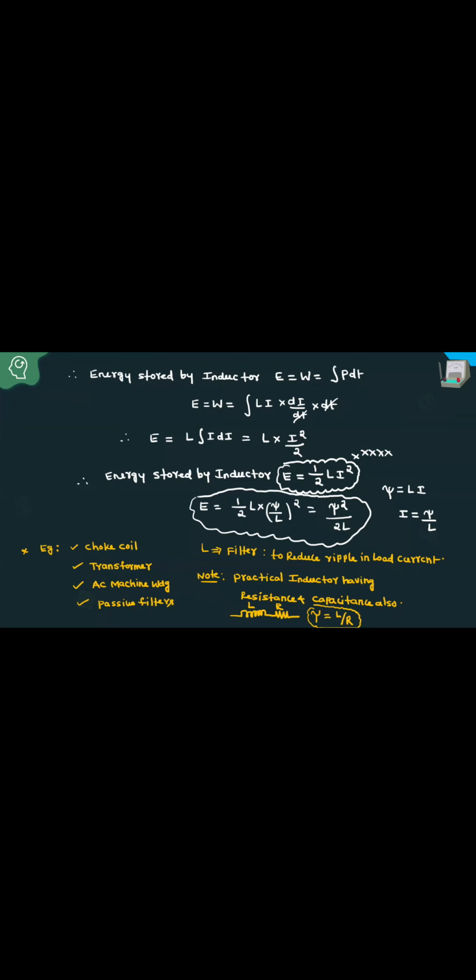Resistance, okay. But how do inductors have capacitance? Students, we know that an inductor is nothing but one core, and on the core we place one turn. Again, on this turn we place some insulation, and then we place one more turn. Like this, we can construct the inductor. That means in an inductor, this is one turn, this is another turn, and in between there is an insulation. This is one conductor, this is another conductor. Two conductors are separated by some dielectric material.